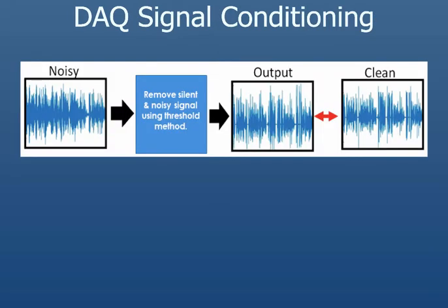It is a prerequisite of DAQs that the measurement system is designed to maximize the quality of sensor outputs and minimize the occurrence of systemic error, as will be discussed in a future lecture. However, it is usually impossible to eliminate all errors and is often difficult to achieve sensor outputs of a suitable amplitude.